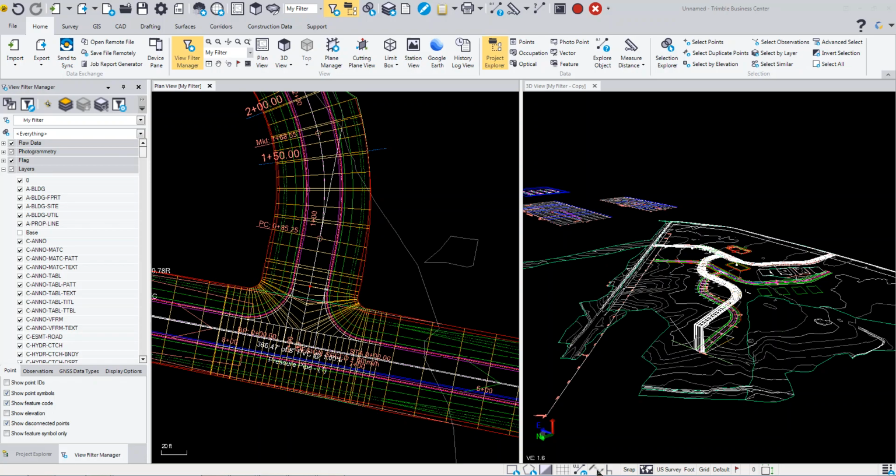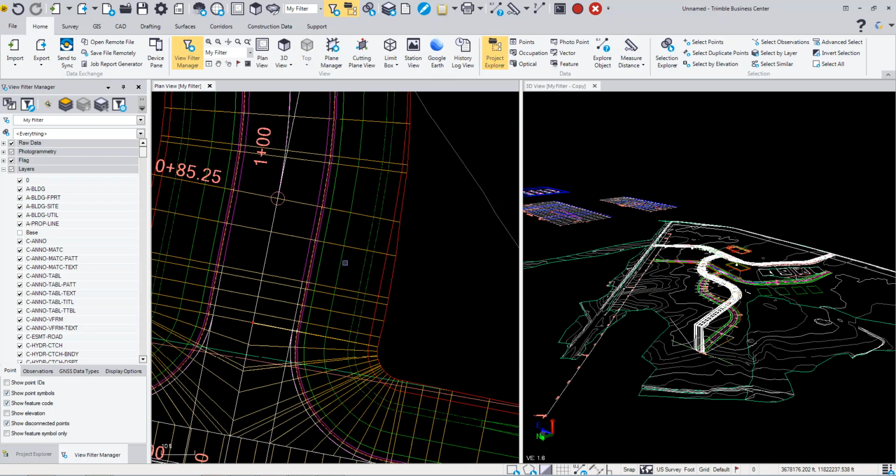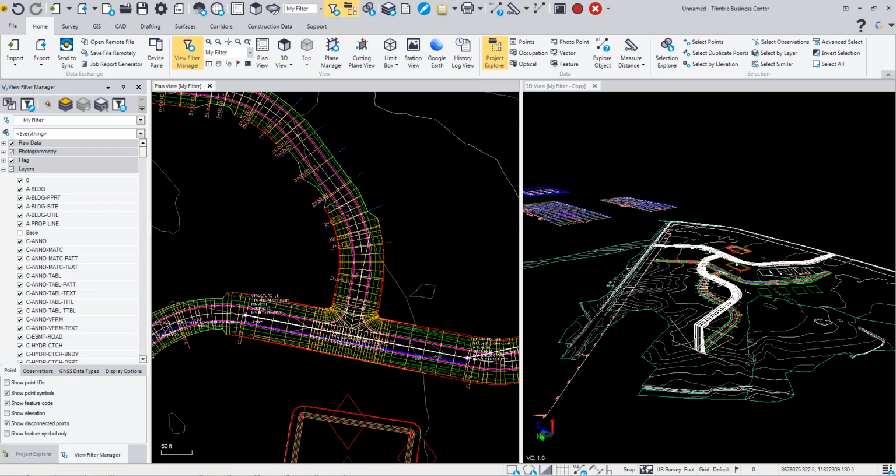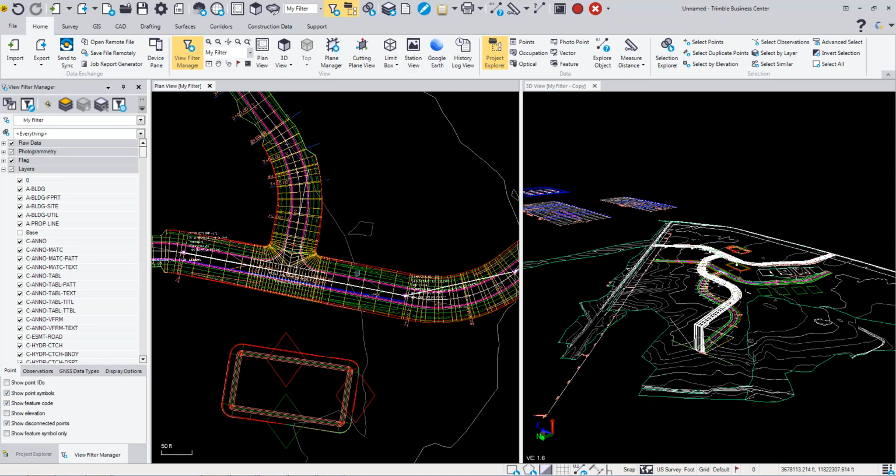To the right of that is the display lines as solid lines or dash lines. So if the line style has a dash or it's got a line style associated with it, by toggling this, you can see here it's going to show all lines as either solid or show them with dashes and their line style. I don't think I have any to display, but that's what that command does. You can see there in the sidewalk, it displayed them a little bit differently in that area. They have a different line style associated in those cut fill areas.